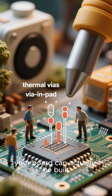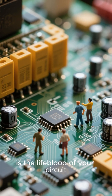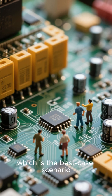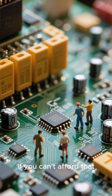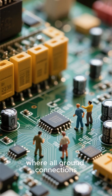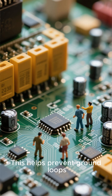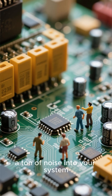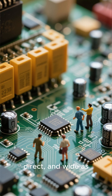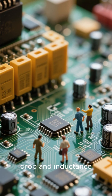Power and ground distribution is the lifeblood of your circuit. We've already mentioned using dedicated planes, which is the best-case scenario. If you can't afford that, use a star grounding topology where all ground connections meet at a single point. This helps prevent ground loops, which can introduce a ton of noise into your system. Keep your power and ground paths as short, direct, and wide as possible to minimize voltage drop and inductance.